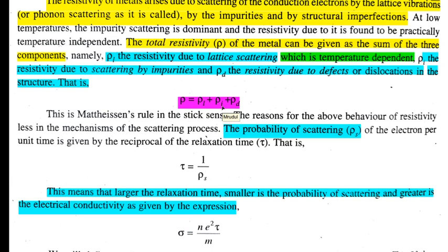Okay, and maybe a physical impact, maybe a reorientation of atomic positions, or maybe a temperature gradient dislocates the host ion and so on. So certain stresses, maybe temperature stress, maybe physical stress, can be a cause of the defect, and that is called a permanent defect, which is again independent of temperature.